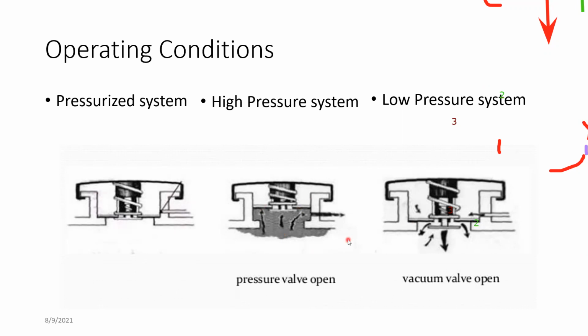In addition to that, this is the normal operating condition. After it's completely open and the system goes over the pressure limits, this opens and the liquid coolant is sent out. Then the valve is closed again. Once it closes, it comes back to this scenario, that means a pressurized system, right?